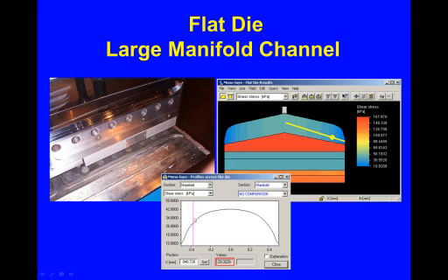We go back to a certain distance and say, okay, the degradation appears to start right about this point, and we can do the same thing on the graph. We can move back to about that point in the position of the graph, and we say, what's the stress level right there where we see that it's still acceptable, and we find the value here of 30 kilopascals.